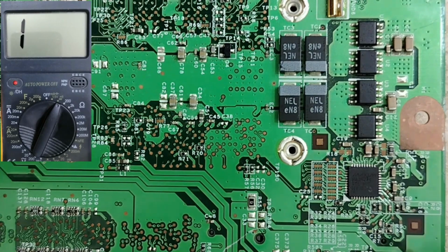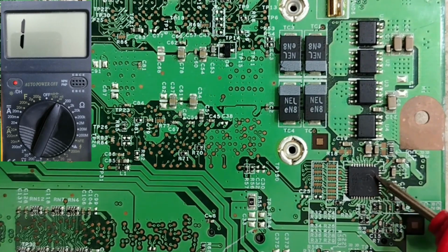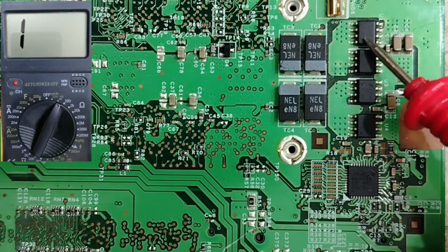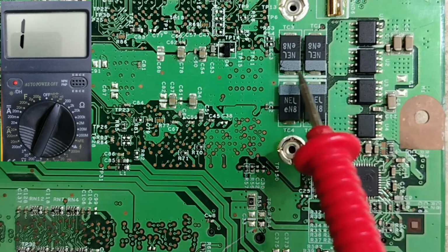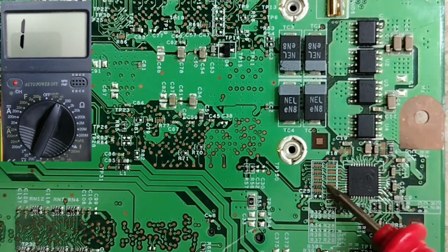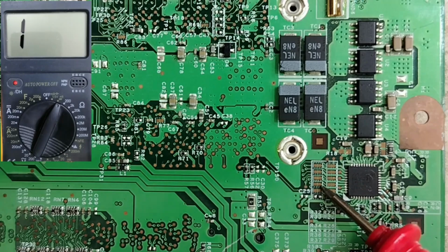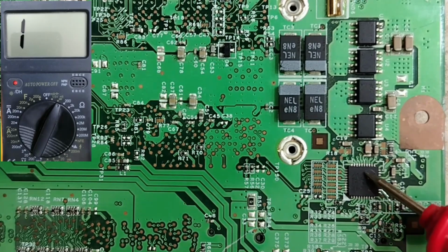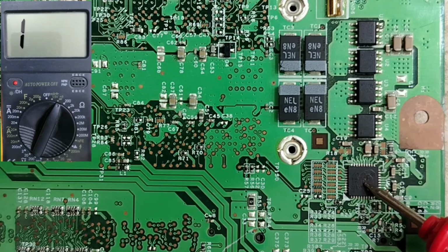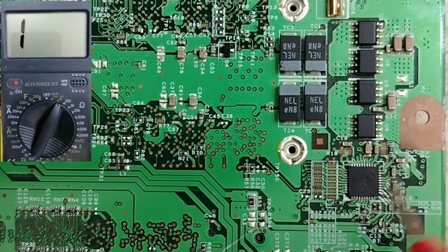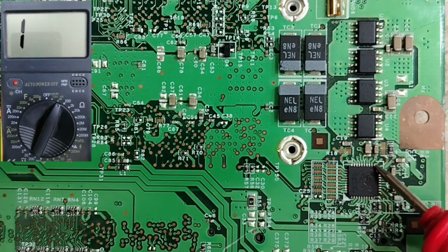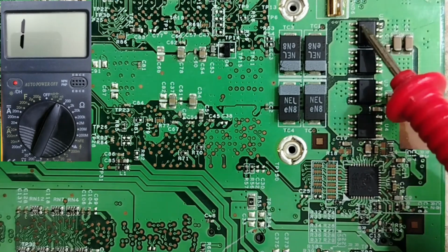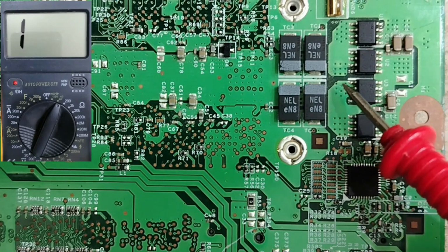In the CPU circuit. So as you can see here, this is the CPU control IC. Here we have MOSFETs, 10-10 capacitor. So this is the first channel here, and this is the second channel. Do you see this part here? This is the CPU IDs, because in order to generate the VCC core to feed the CPU, the IC should receive first these IDs, as you can see, and based on these IDs it will generate the control signals for these MOSFETs in order to generate plus VCC core.